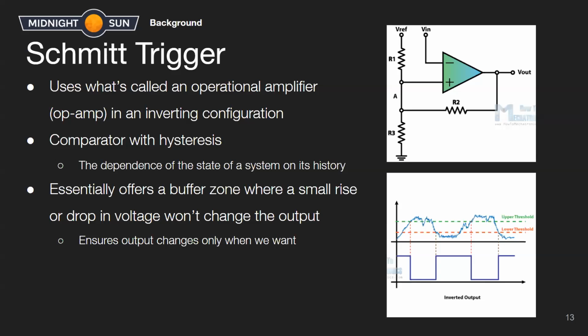And then a Schmitt trigger. When I showed you that RC filter and I bounced it a whole bunch, you still saw that the voltage was changing, just it never hit 3.3 volts. But we still don't want the voltage to be between 3.3 and 0, because when you're working with a digital circuit, there's basically two types of signals. There's signal high and signal low.